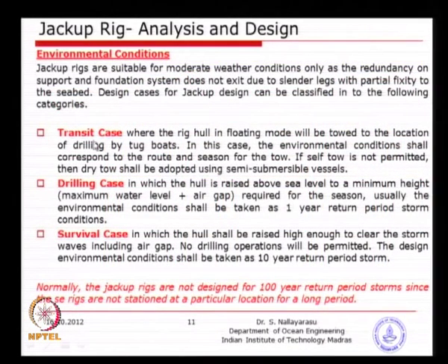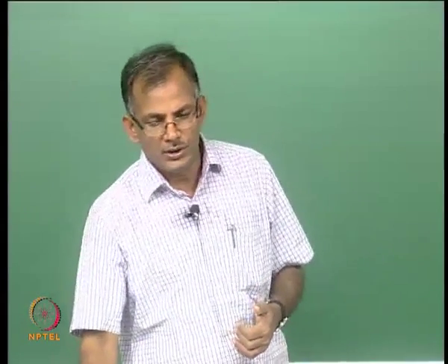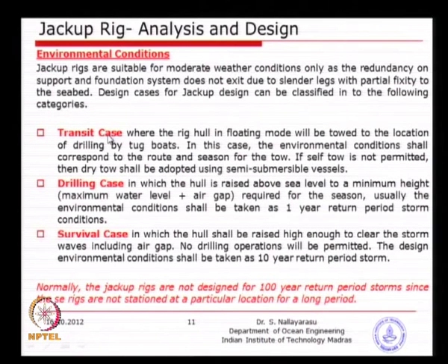With regards to the design environmental conditions, we just need to understand one important thing. This being a temporary structure, it has 3 phases. The phase during which it is always going from one place to another place is the transit case, where it is going to go through several conditions. Sea state conditions could be different from what it used to be operating in, but of course, we have a choice. Some of the jackup rigs can be towable, that means you can use a tugboat to tow in floating mode.